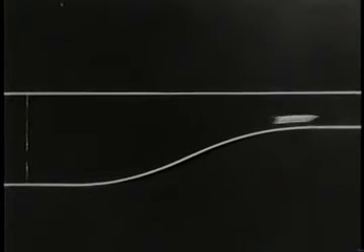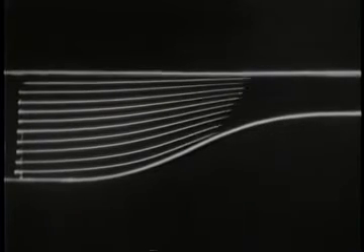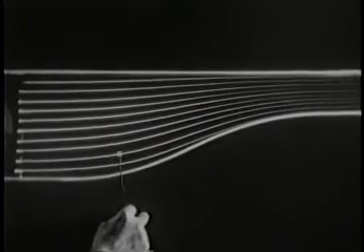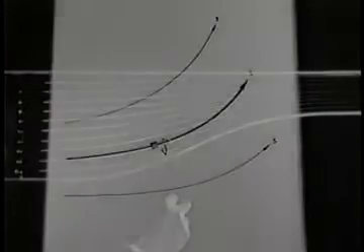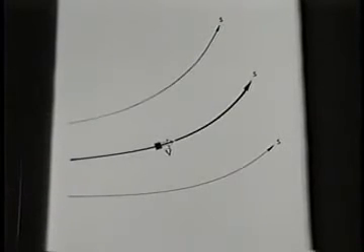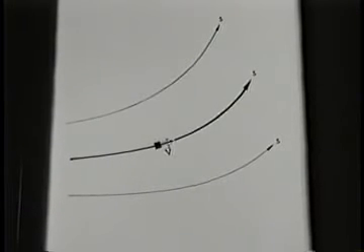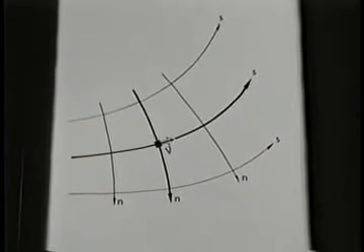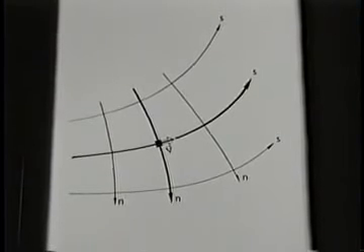The velocity increase in the contraction is coupled to the pressure decrease by Newton's law of motion. Let's see how. Here, the bubbles mark many streamlines. Let's imagine that this is a typical fluid particle. For thinking physically about the problem, it is helpful to use the streamlines S and the normal trajectories N as curvilinear coordinates. First, let's look at the forces and accelerations along S for the typical fluid particle moving with speed